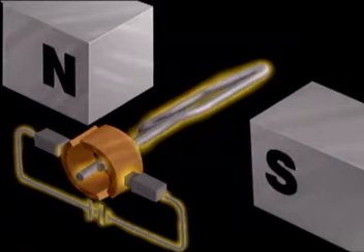Because the armature is U-shaped, its flux lines change direction relative to the magnetic field flux lines on opposite sides of the armature. To see this more clearly, let's look at a graphic representation of a side view of the armature. The two circles represent the left and right sides of the armature. On the left, current is flowing toward you, represented by a dot in the circle.